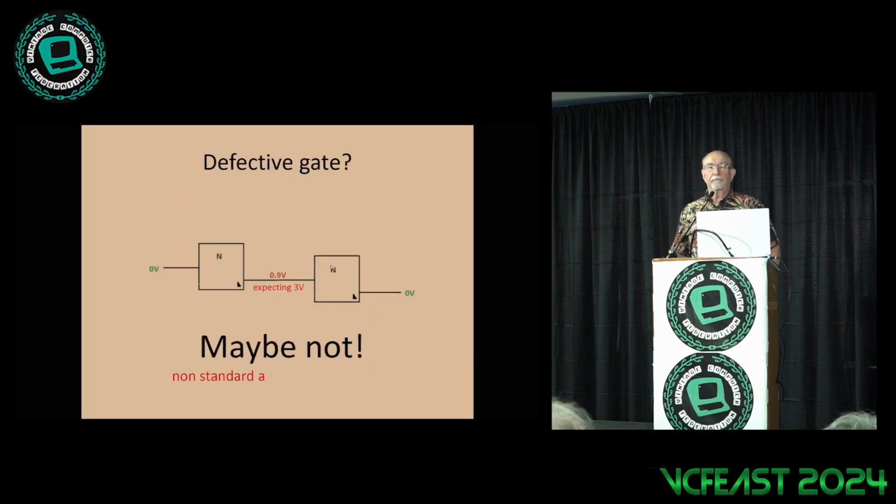I was working with a couple of people restoring an 1130, and they had a logic analyzer on, and they saw something weird. They saw 2 NOT gates, 2 inverters in a row. 0 in, at the far end is 0, that's right, but the middle wasn't +3. It should have been, right? In SLT, +3 is a 1, a logic high, and 0 is a logic low. So they put the scope on it and saw it was a fractional voltage, and thought, well, maybe we've got a short or some problem. But that wasn't true in this case. It was working perfectly fine.